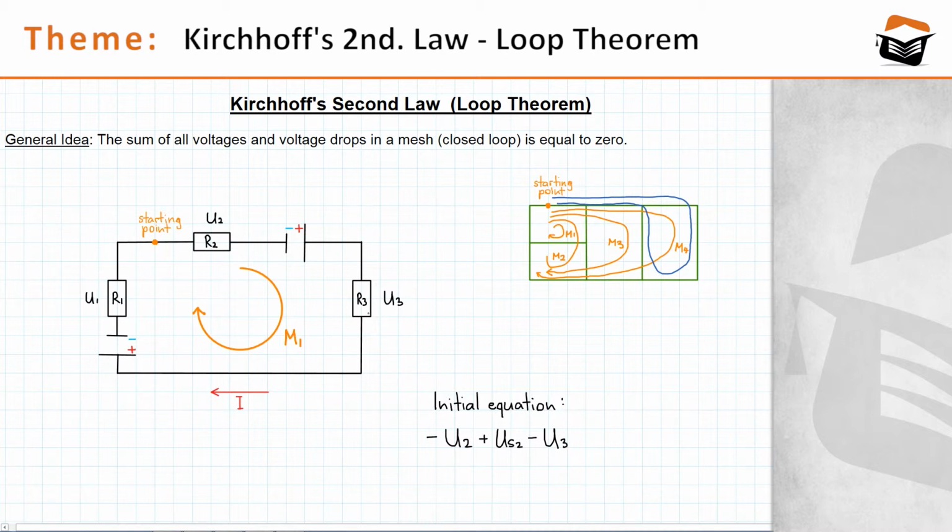And now I have another voltage source. However, be careful with where on the voltage source you have a positive pole and a negative pole. Previously, we had a negative pole coming first and then a positive pole on the path. So we treated that voltage as positive. Here, on the other hand, you encounter a plus pole first and then a minus pole.